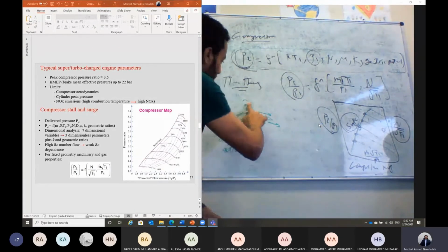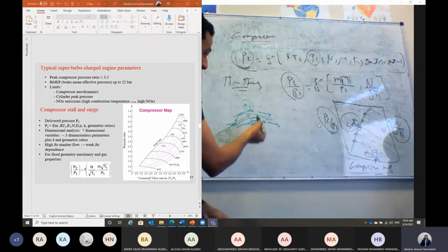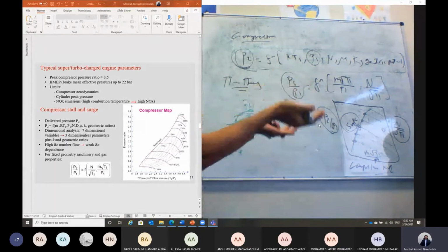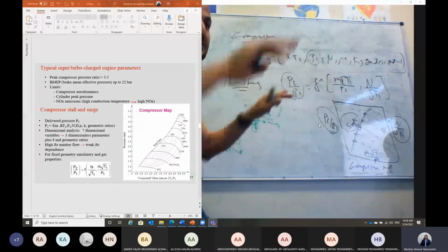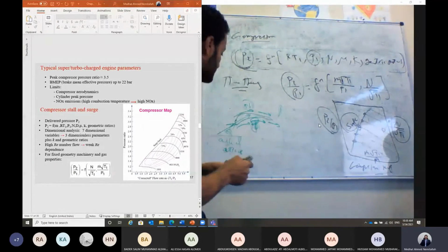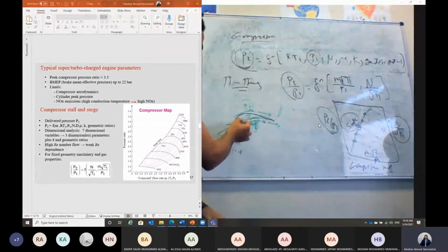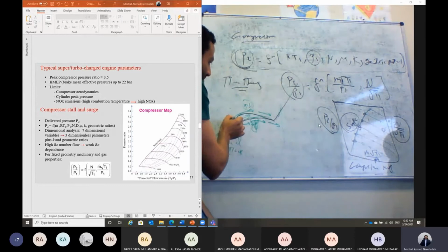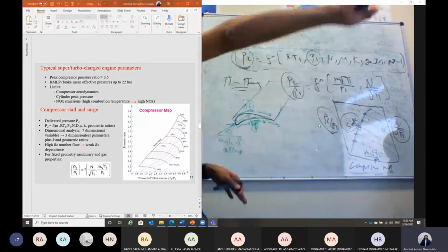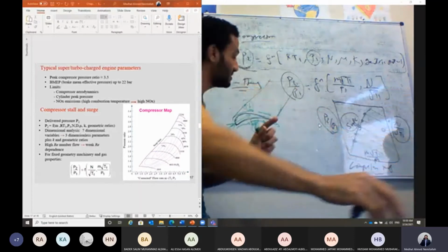Sorry, the pressure here will be low, and the pressure here will build up, and that's why we should have a kind of lift. That's why the airplane will be just flying due to the effect of the difference of pressure above and below the aerofoil. If you look at the airplane, this is the size of the wing of the airplane. It's just something like this, but it takes the shape of an aerofoil.